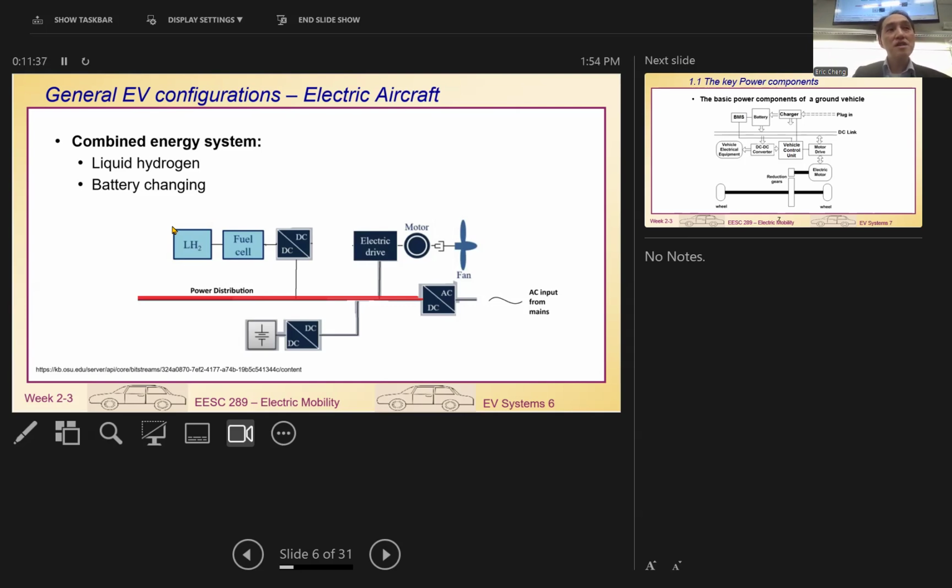And then liquid hydrogen has a second advantage. That will be for the cooling. In some of the compartments, you do need to have cooling. Once your liquid hydrogen evaporates and becomes hydrogen, it goes to the fuel cell. And for the engine, motor, fuel cell, drive system, and power distribution, you need some cooling. So you can use your hydrogen for cooling. So that's one of the reasons they have chosen to use hydrogen. That's a huge development here.